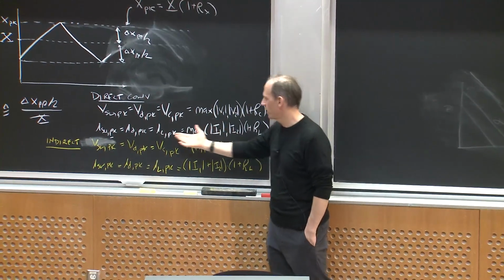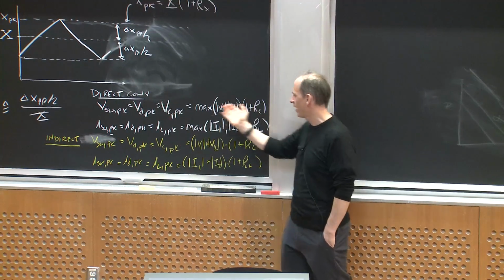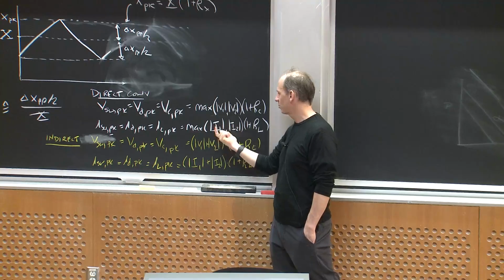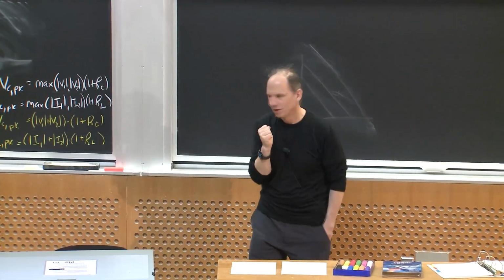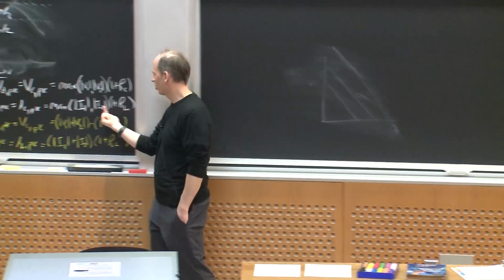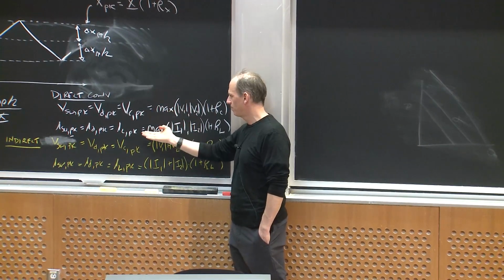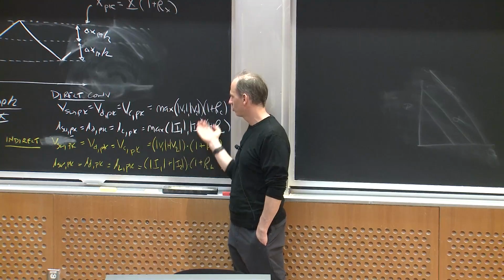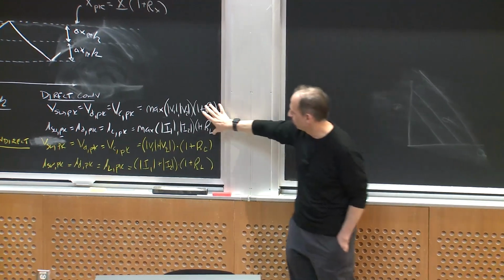And likewise, we can talk about the switch current and the diode current peak values, which are related to the maximum of the average input and output currents. Okay, so for a buck converter, the output current is the bigger one and the input voltage is the bigger one. But we see peak stresses in voltage and current that are related to the maximum of the input and output DC waveforms and the ripple.